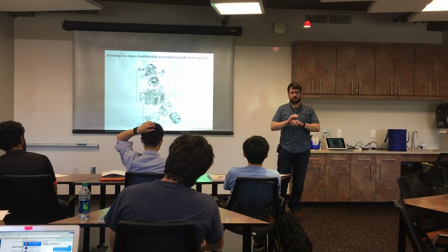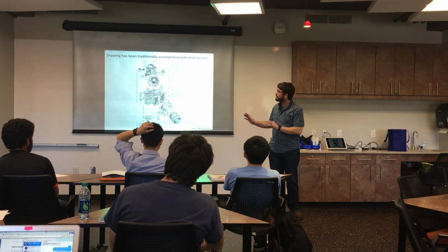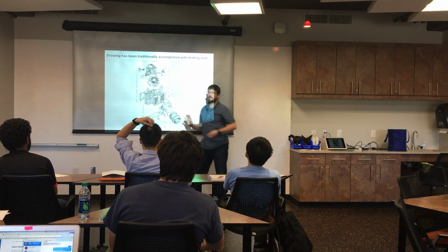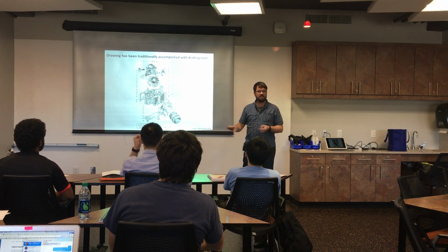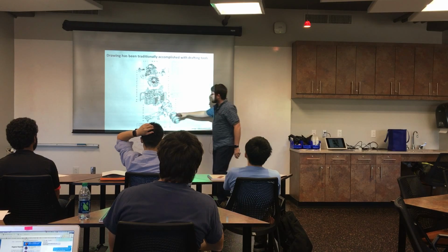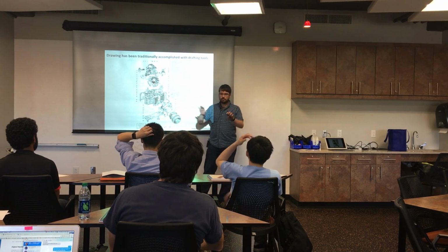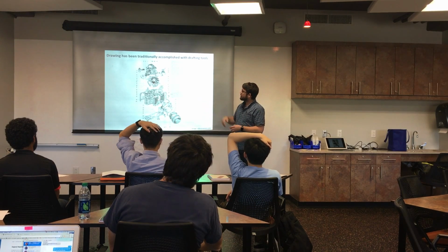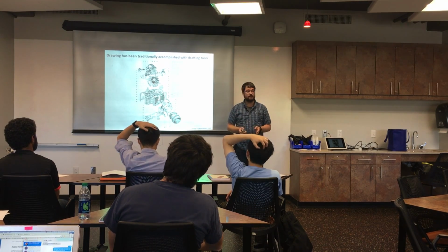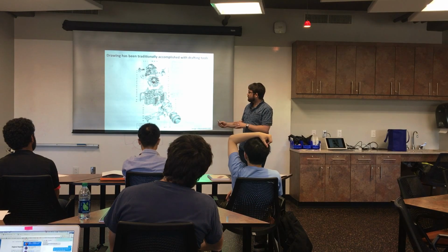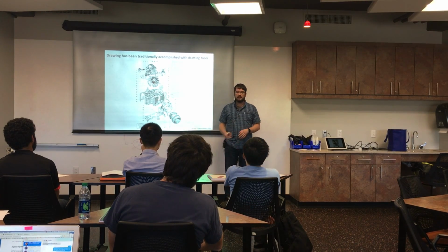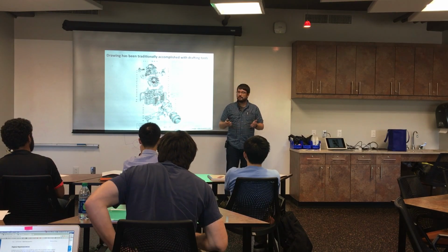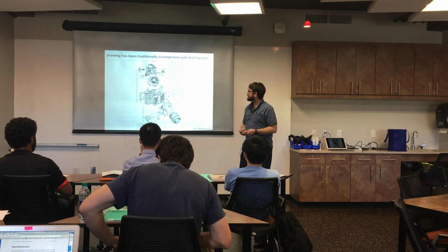So draftsmen were artists, and this is what's called an exploded drawing, where you see the device busted apart into its pieces so we can see how they go together. It's an assembly drawing. Each of these pieces would have had a separate two-dimensional drawing that tells the manufacturer how to make that part. And then this assembly drawing would show somebody on the line how to put it together, or somebody that's repairing it. But now I would say the art of finding people that can make a hand drawing that looks that good is all but lost, most likely, because we all use computer-aided design now.